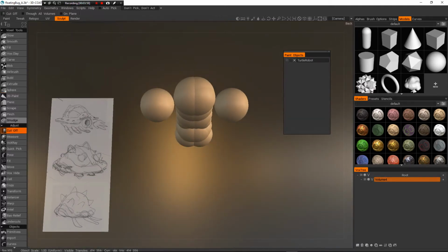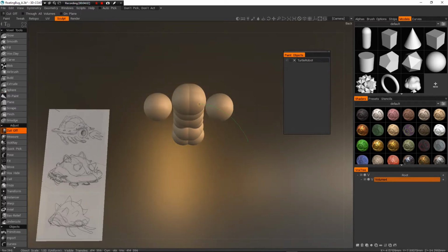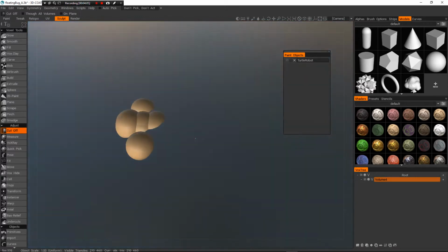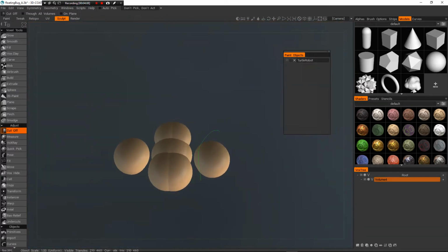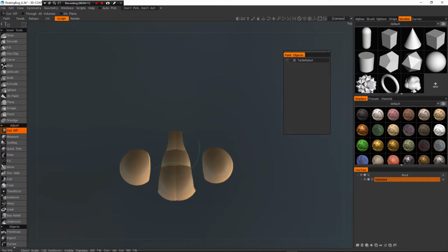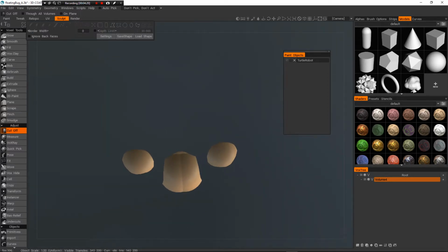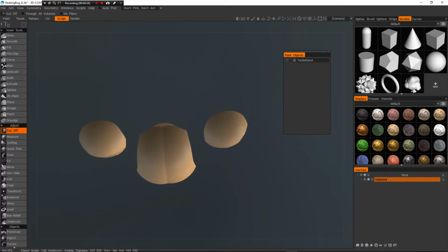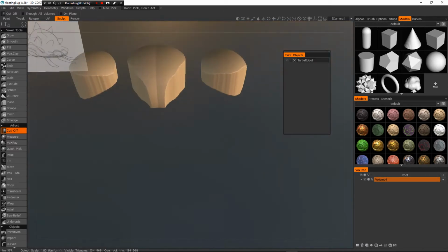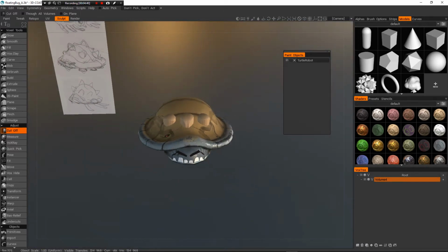So I'm going to use my cutoff tool. So again, still in the sculpt room. Just using my cutoff tool, I'm going to cut off the parts I don't want. Okay. So the brush type I'm using here is a Lasso Brush. In cutoff mode, it's automatically going to use a marquee type brush. So either the square, rectangle, polygonal lasso, circle, or ellipse tool. All right, then I can bring back the visibility of my turtle.